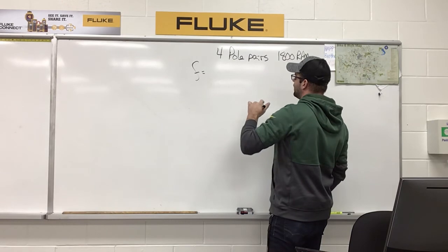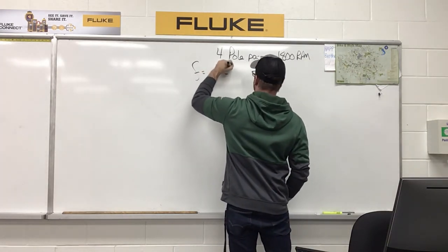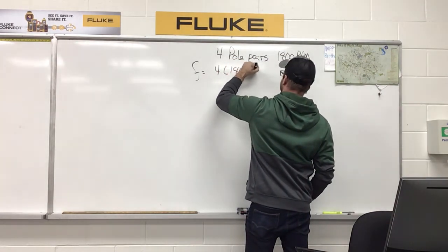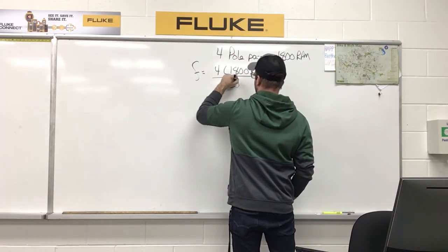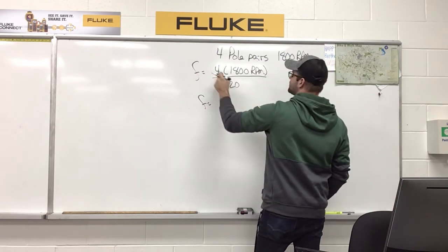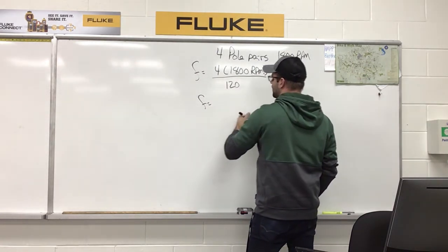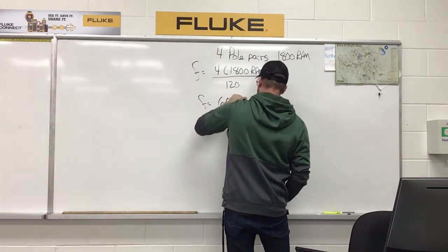So 4 times 1800 divided by 120, so that's 7200 divided by 120, and you'll find that this has a frequency of 60 hertz.